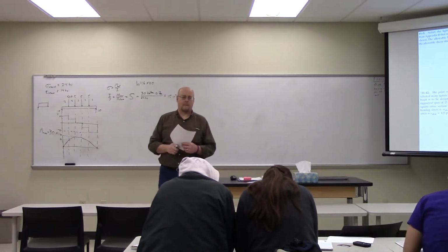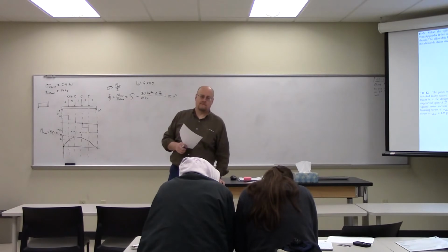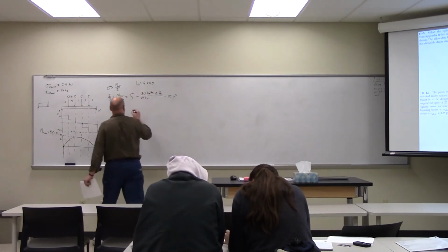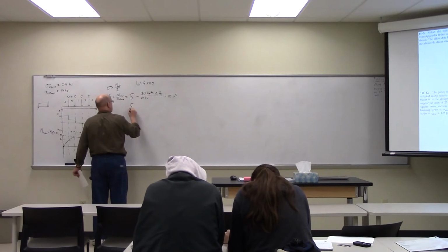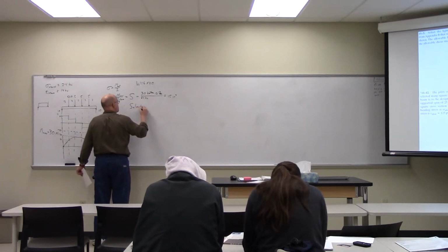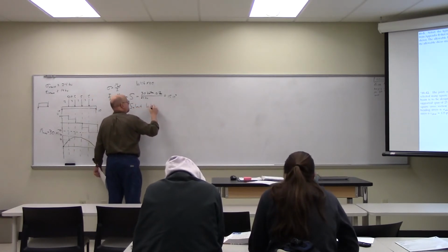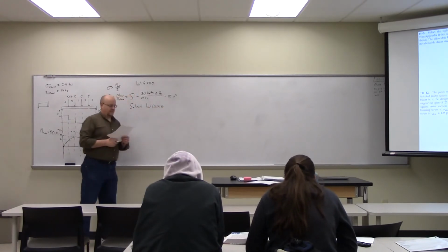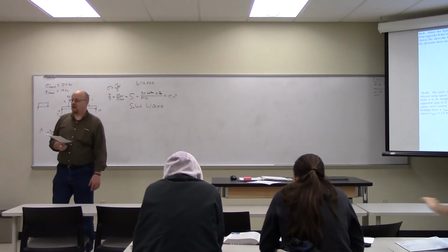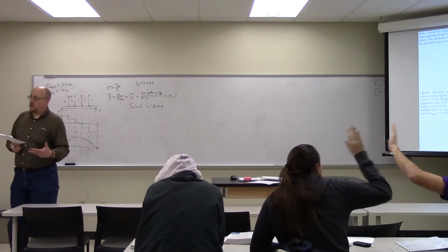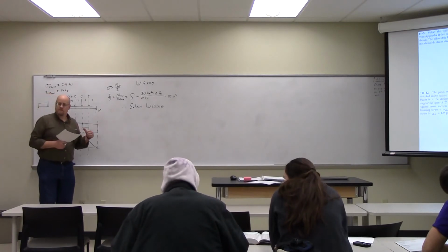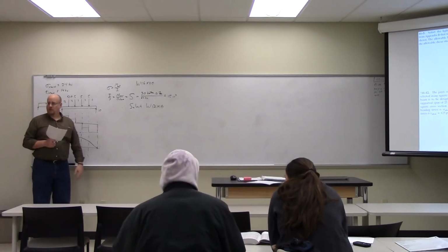So we're going with W12 by 16. That'd be correct. So the 12 by 16 is the lightest one that has a section modulus over 15 among the wide flange I-beams.